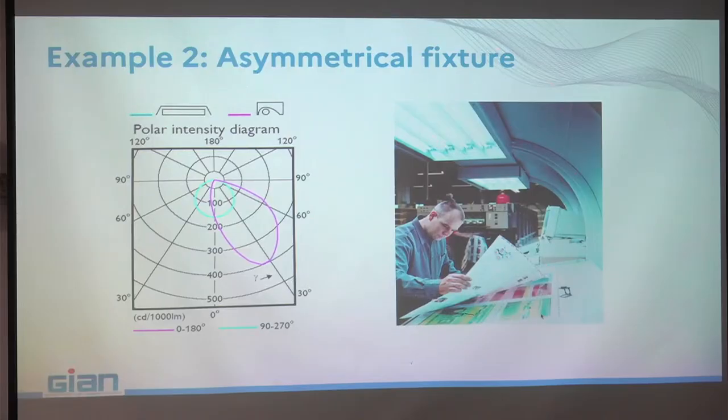Okay? You illuminate from behind, and you can even choose the angle of the maximum illuminance to the direction here in order to avoid, for a standard height worker, the shadow from his head. That means the flux passes above him and then illuminates very well his working plan.